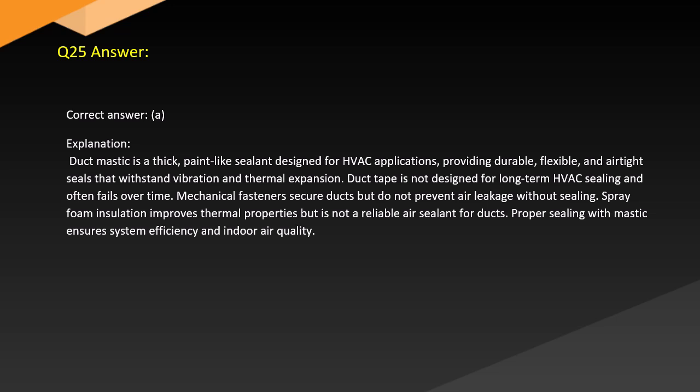Mechanical fasteners secure ducts but do not prevent air leakage without sealing. Spray foam insulation improves thermal properties but is not a reliable sealant for ducts. Proper sealing with mastic ensures system efficiency and indoor air quality.